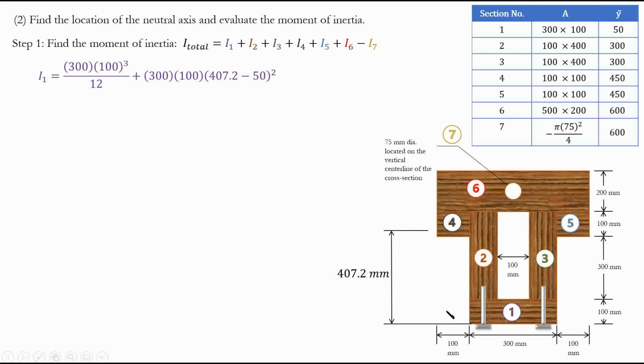And someone might think, oh my god, this is really complicated. From this shape, I have to again see what this distance is from here to here. Again, I have to look at my numbers. But the answer is that is not what you have to go through. Let's not make it that complicated. Do you remember the table that we created here? If you construct that table, that's it, right? You can just see what d is. d is going to be y bar minus y tilde for each part. Y bar minus y tilde.